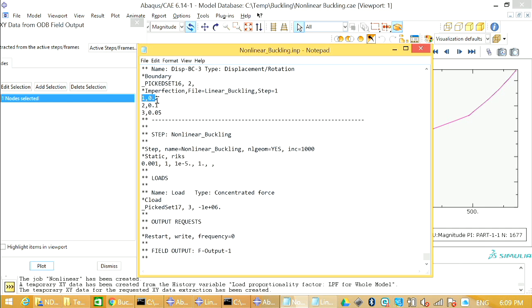And we need to set this one line, two lines, or three lines. Basically, what we're doing through each of these lines is to modify those eigenvectors that we obtain in the first step. To give you an idea, those eigenvectors are basically the coordinate displacements in the x, y, and z direction, right? So by imposing this amount, let's say 0.2, we are adding that amount to each of those displacements. So any of the components of the eigenvector will be modified, right? Based on those new eigenvectors, we're going to run the nonlinear analysis, because we are incorporating that imperfection.